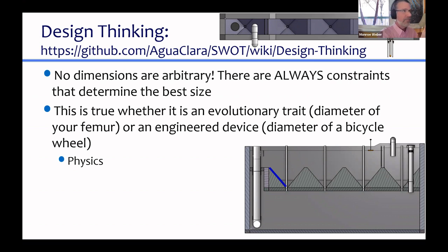And there's Michael's question: what about that slope in the hopper? Where did that come from? Well, what would you like to have happen in this hopper? You would like it so that when you pull the plug out of that hopper, the hopper would drain, meaning all the sediment that's sitting there would slide down and go out the hole.